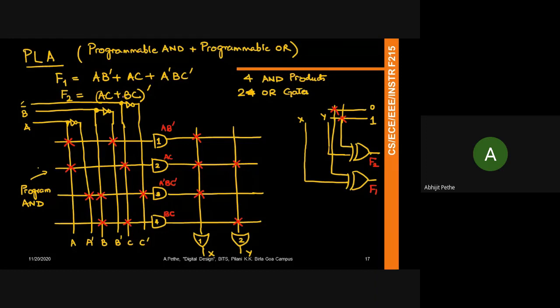And sometimes you have to generate more than one function. This chip gives you the flexibility of only generating 4 product terms, which means that if you're going to generate 2 functions, these 2 functions should use either all or at least a few of the same product terms.